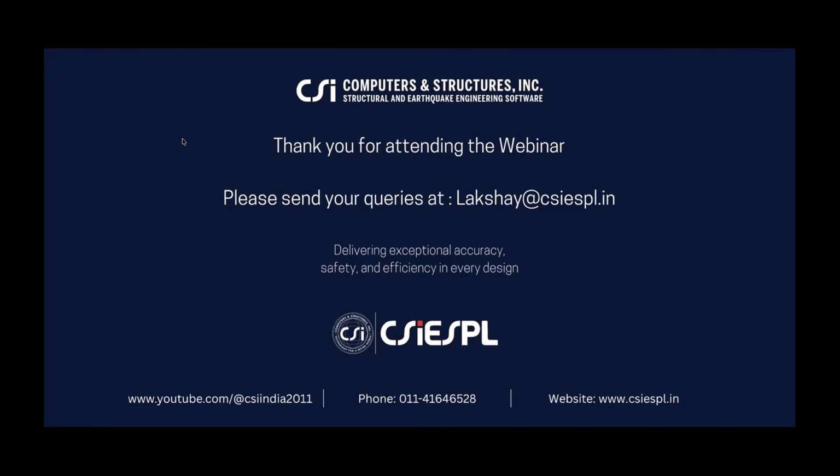Deflection is checked by the program. For this model, we did not use it, but for building systems, you need the deflection check. The program performs it for the beams. That result is already available, which I did not discuss. Yes, you can use tension-only members. That is possible. We have the option to assign tension or compression-only members, but the analysis case must be of nonlinear type for that.